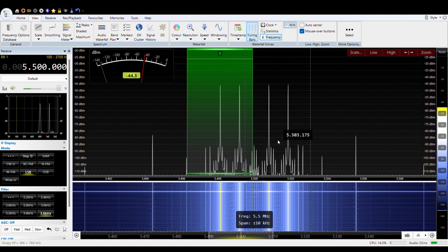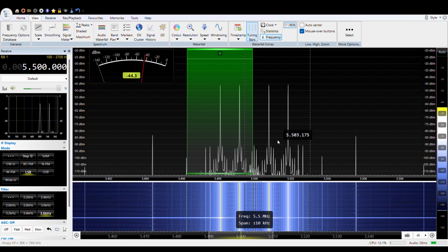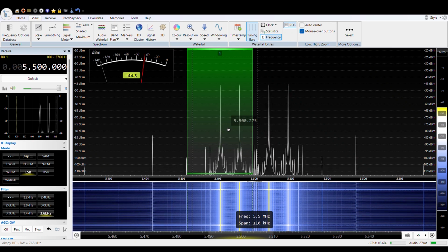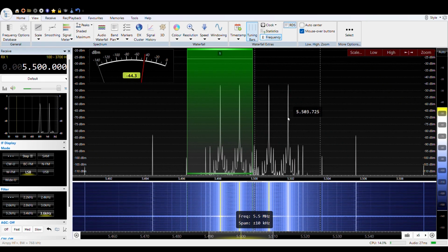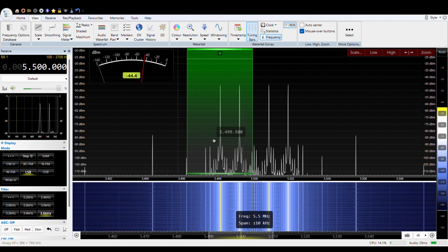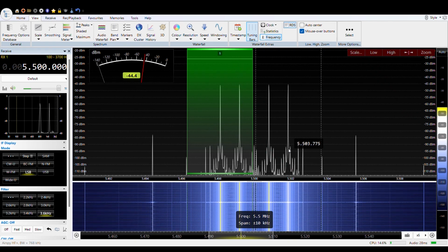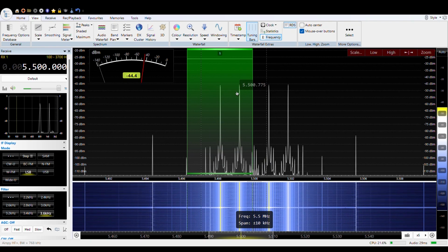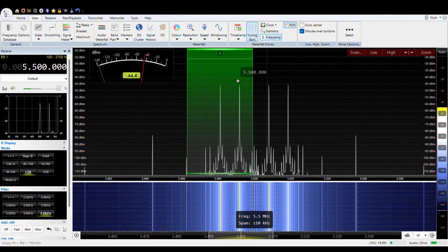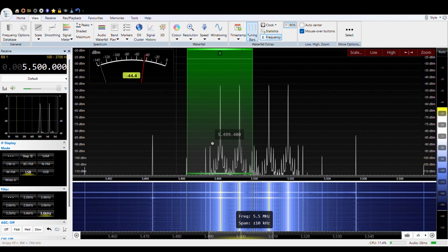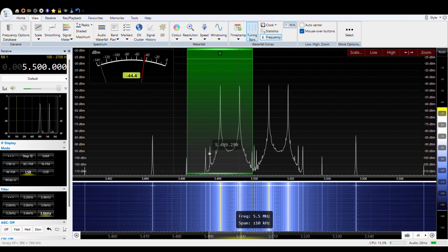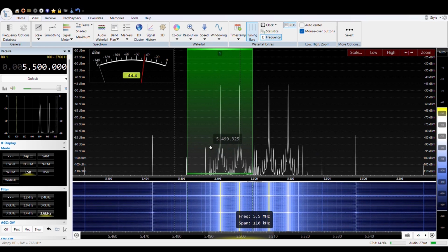Now, the real gem to try to pick out of this would be, well, what's the third order intercept? And again, this is not a spectrum analyzer. This is a spectrum viewer, and I don't want to read too much into it, because if it was a true spectrum analyzer, we'd be able to find that third order modulation signal coming through, and none of these are them. What I've done, I played around with this for about an hour or so and changed the magnitude of the signal strength going into the stage, and I could get these four peaks to go up and down, but none of these were moving at three times the rate, which is a requirement for that third order intercept. So it's really not picking it up. It's not showing it anywhere on there. But no worries.